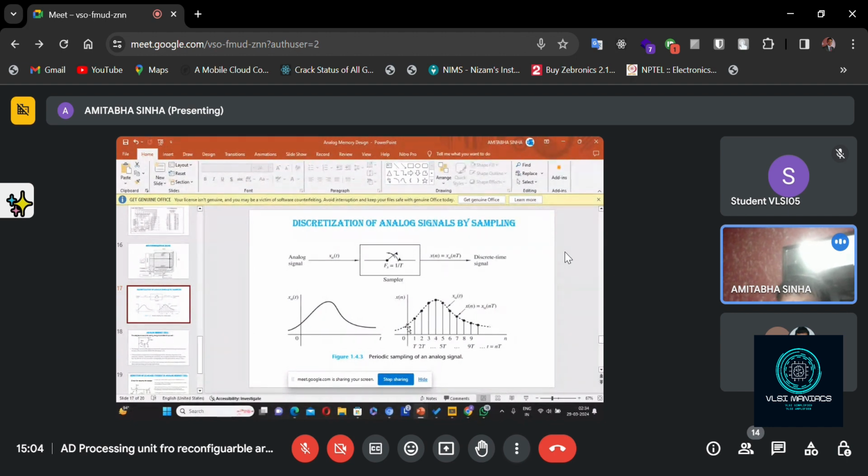So these values are discrete analog. So how will an analog signal be stored? We all know that an analog signal can be stored in a capacitor, because a capacitor is basically a charge storage device, and from the well-known formula Q equal to C into V, where C is the capacitance. So we will utilize this concept for storing analog data.